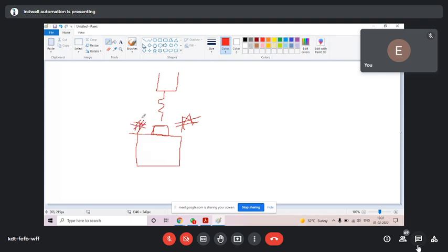Suppose the process is, very first, as you start, you put the metal on the workstation. It is a manual system actually. So the operator will put the job on the workstation and start the air valve first. Air valve should be on for 3 seconds. How will the operator operate? The operator will press the switch to turn the air valve on and will see the clock: 1, 2, 3. And manually will turn it off.